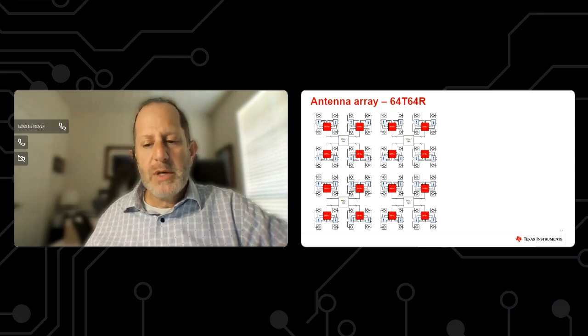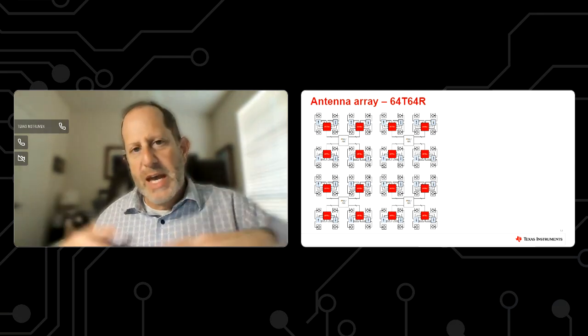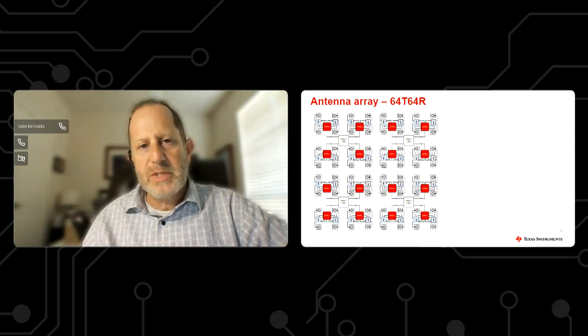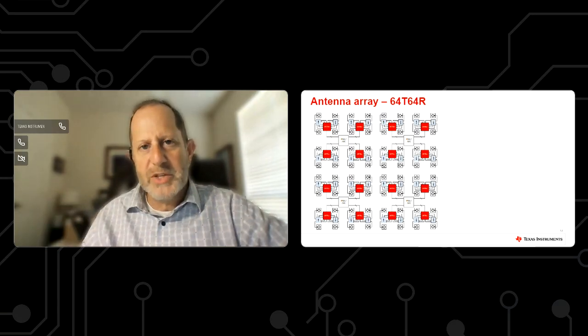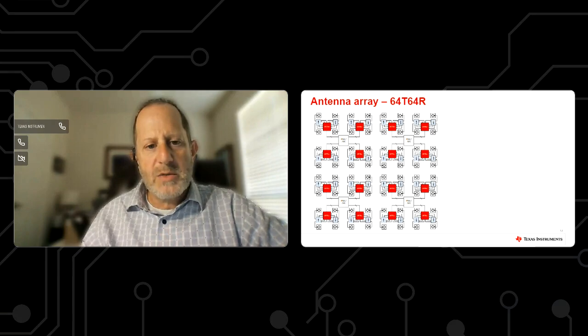Temperature effects, things like that, might adjust the phase at different times and different points in its use. So having that flexibility to be able to independently adjust the delay on each of those clock elements to kind of calibrate that out can really do wonders in order to keep our device perfectly synchronized in all cases. So yeah, these are areas that we are paying a lot of attention to in order to synchronize across multiple devices using our clocking solutions.